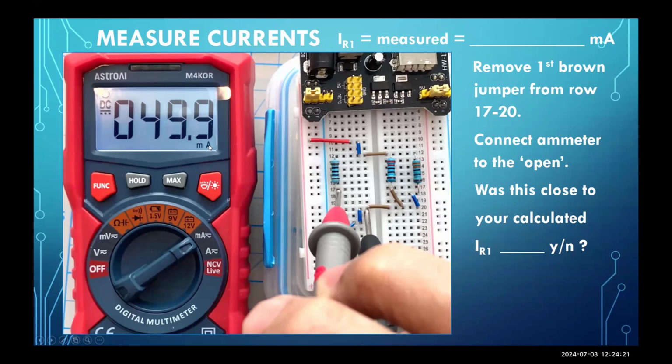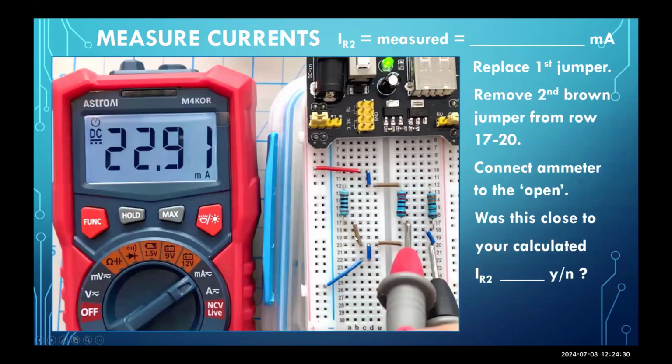The answer is yes. Now, to measure IR2, you fill in the number up here and you answer yes or no down here. To measure IR2, you have to rebuild this jumper for the first resistor. If you don't rebuild the jumper for the first resistor, you're not going to get the 22.91 milliamps. No way. So what I'm doing here is removing the second jumper. It says directions: in order to find the measurement for R2, I have to replace the first jumper, remove the second brown jumper, and then connect the ammeter to the open.